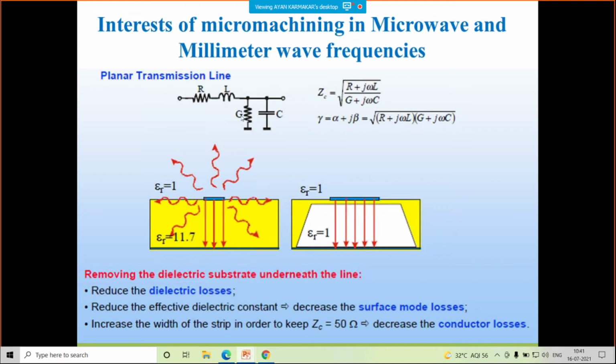How can you reduce this dielectric loss with the help of silicon micromachining? How can you get rid of the bulky silicon beneath your antenna, so that your antenna effectively sees a permittivity of around air, because it is seeing nothing but a thick column of air and a very thin layer of silicon?